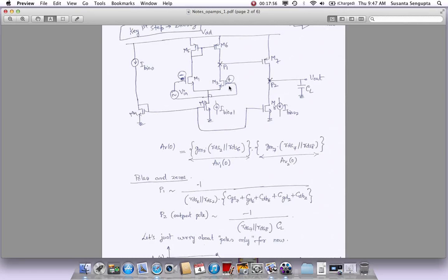You can take this thing and you can make a small signal model, and you should do that as a side exercise. You should do the derivations, and finally when you find the complete transfer function of V out to V in here, you would see all the poles and zeros there. What I'm showing you are some approximate expressions for these poles and zeros that we are deriving intuitively without getting into the big derivation part of it, and seeing how, as a first cut, as a first order approximation, you find them quickly, and how they match up. They should match up pretty close to what you get from a complete derivation.